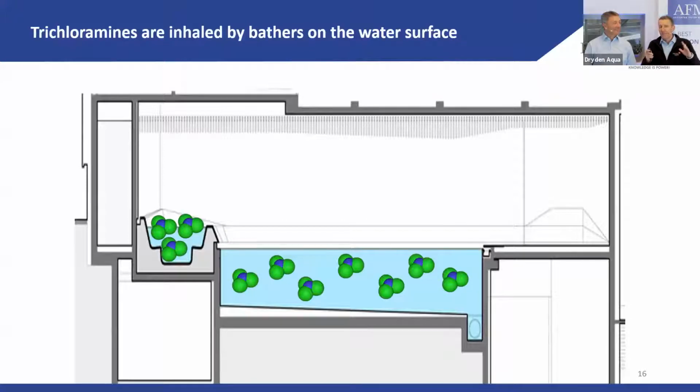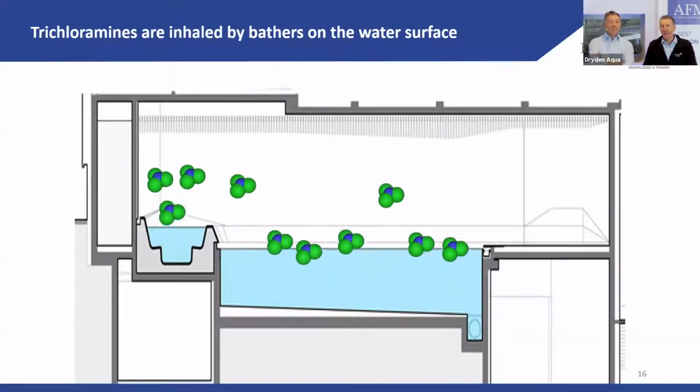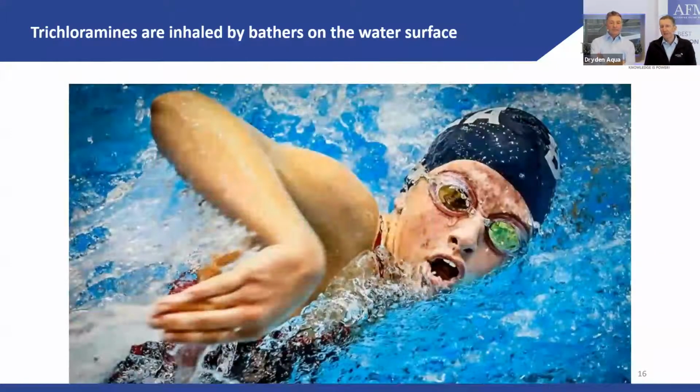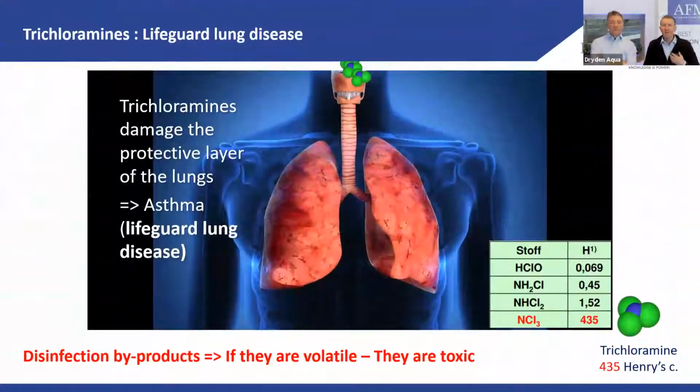But the much bigger problem here is really the health effects it has. Because it gases out, bathers and swimmers are inhaling the trichloramines that gas out of the water. Inhaling them means that the trichloramine that enters the lungs is able to remove the protective layer that we all have in our lungs.